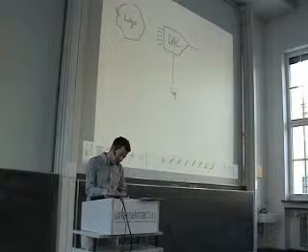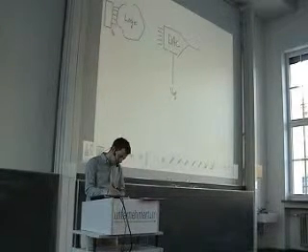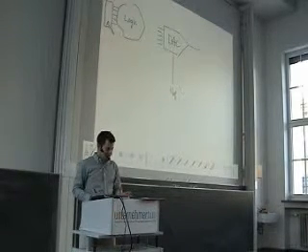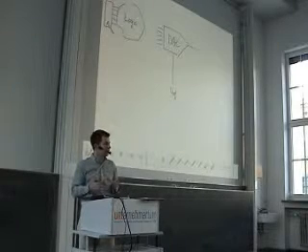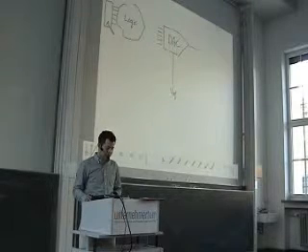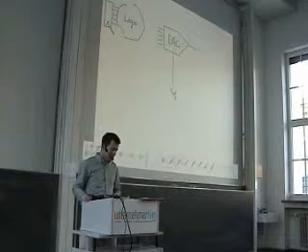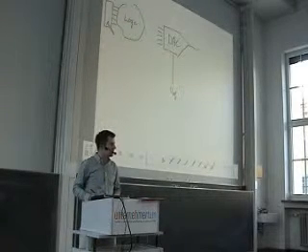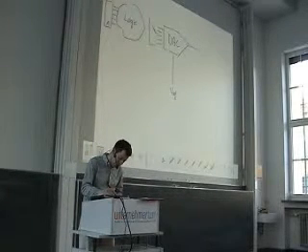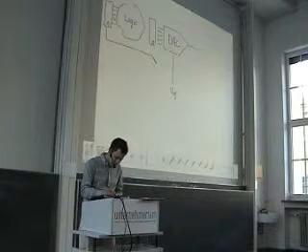Well, we always have synchronous logic, so somewhere in front of this logic is a register that issues the data into the logic, which computes the signals for the DAC, and then the DAC converts these signals into an output voltage. To avoid the effect of the different path lengths through the logic and make these signals switch all at the same time, we need a second register here, which is also controlled by a clock signal.